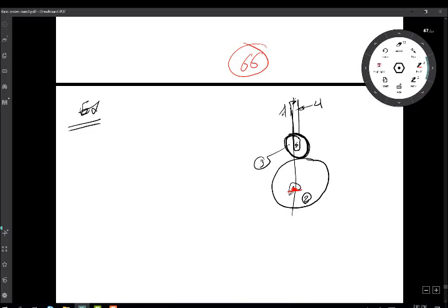This point here is easy to find: it is 1,2, common between 1, which is the ground, and 2, which is the cam. That's the pivot. Another one which is really easy to find is the pivot over here. This pivot is point 3,4, common between 3 and 4. All my pivots are very easy to find. Also, once I have rolling contact, that's a bliss, because the actual point of contact, don't forget that's a higher pair, is a point of common velocity, since the roller is pure rolling. So I can say this is 2,3 here.